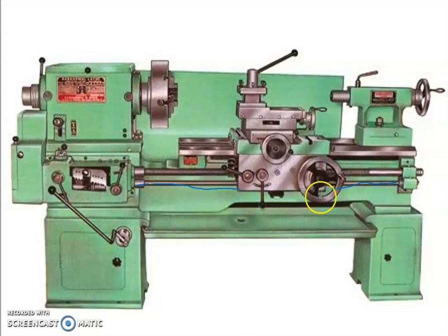This feed rod will allow the carriage assembly to move to the left side, again right side, as you rotate this hand wheel. So we can move this to the right side, again to the left side by using the carriage, by using the lead screw, sorry, the feed rod. This is the feed rod. We can see another rod is there. Don't confuse, this is the feed rod and this is called the screw rod. So this we'll discuss next.